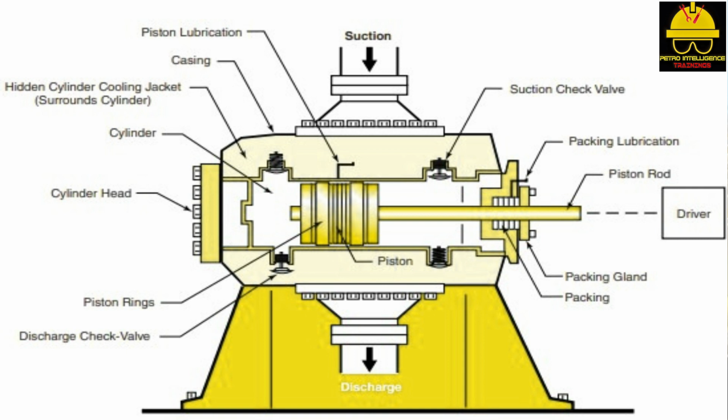Most piston compressors have 1 to 4 cylinders. Each cylinder has its own piston, rings, and automatic valves. Common crankshafts can be shared with multiple connecting rods. The same cylinder can be equipped with multiple suction and discharge valves in double-acting compressors.